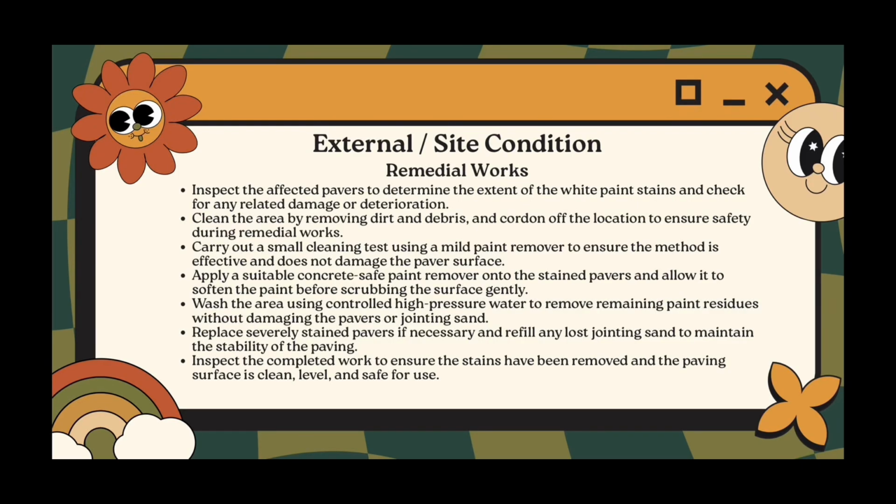For the remedial works, we prefer to wash the area using controlled high-pressure water to remove remaining paint residue without damaging the pavers or jointing sand.